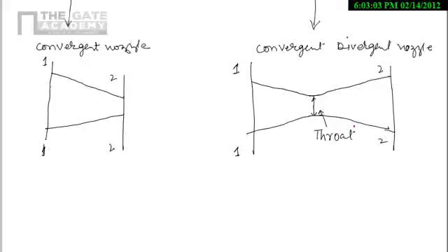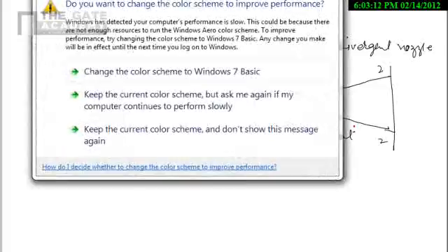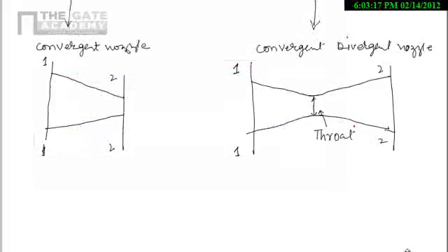Suppose in a nozzle we get higher kinetic energy, that is a conversion of enthalpy to kinetic energy. In a diffuser, the kinetic energy is converted back. The most important parameter for such discussion is the Mach number. The Mach number will decide whether the device behaves as a nozzle or a diffuser. So now first of all, I will define the term Mach number.